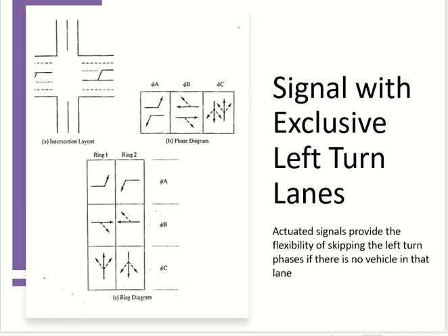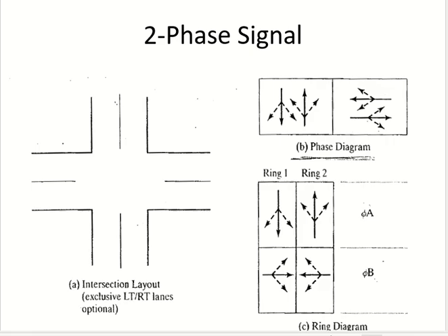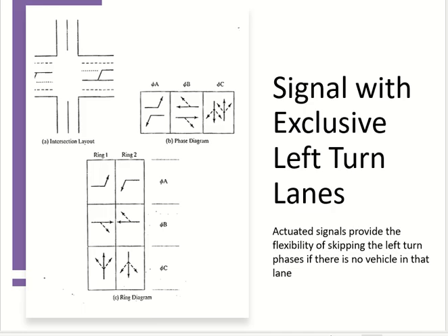Okay. So we had to add the lane because the separate left turn cannot happen without a separate lane. If you keep one lane in each direction and try to add a separate phase for left turn, it will not work. So now you see the changes in intersection geometry because of the changes in the phasing plan.